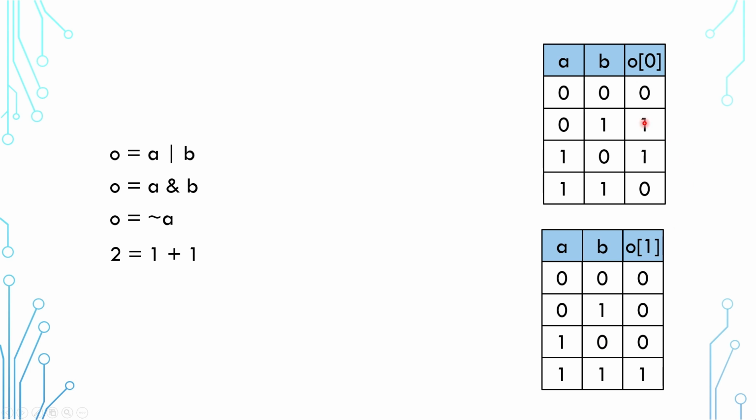These tables are known as a truth table. We can use them to design digital circuits. For example, we can focus on when the output is 1. In this case, output is 1 when A is 0 and B is 1, and we can represent it by using a circuit like this.